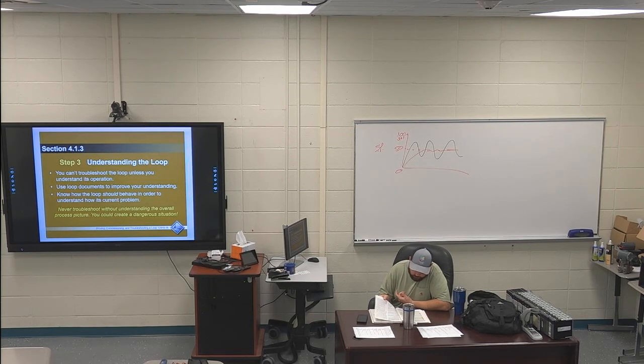This is still in the troubleshooting techniques and stuff like that. On page 24, the last sentence before 415 is highlighted. Start wherever your instinct tells you to start, but always be systematic and logical. I say start at the beginning or the end of the loop, because that's what's logical to me: start at the beginning, check your power supply stuff, and then work your way down.